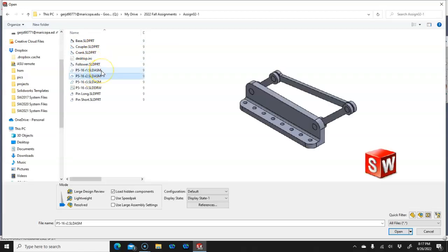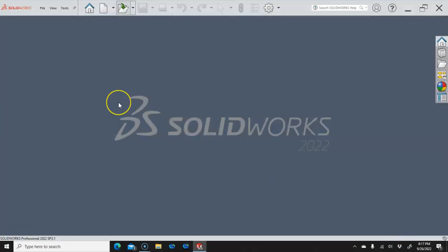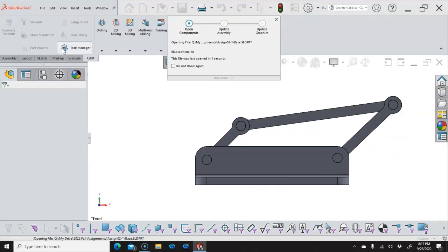And we can have as many assemblies, what-if scenarios as we need, but really only one of these is going to have priority. So if I'm building into this as a subassembly, I want to keep one name, and then I can save as at a stopping point, or possibly do a zip file of the whole folder to take a snapshot at that point. So let's just grab revision 2, since I've modified revision 3 a couple of times, and we'll give it a chance to load.